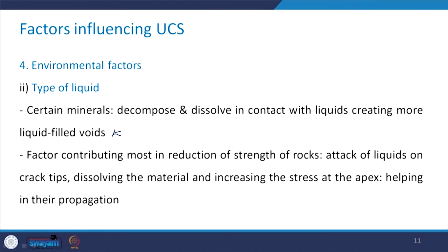Now what happens because of the liquid? When this liquid comes in contact with the rock, there are always some cracks present in the rock. The liquid attacks the crack tip, and depending upon the mineralogical composition of that rock, whatever mineral is present at the tip of the crack gets dissolved in the presence of that liquid, and that increases the stress at the apex. The moment there is an increase in the stress at the apex, that crack starts propagating.